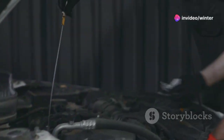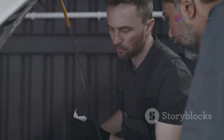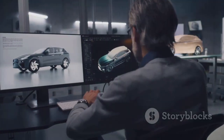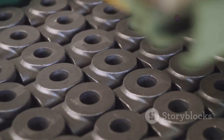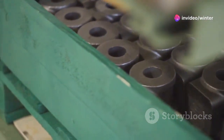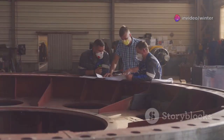They also wear out faster, causing downtime and expensive repairs. Always ask, is that undercut essential? Can you redesign to avoid it? Use pass-through cores or flexible tabs instead of features that require slides. Creative problem solving here saves big money.